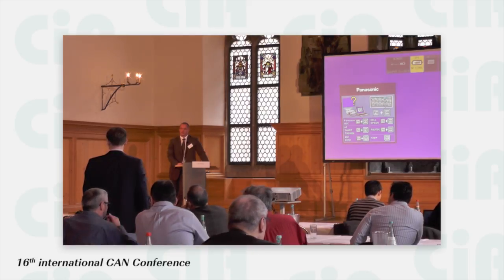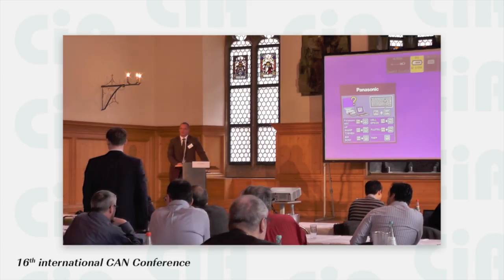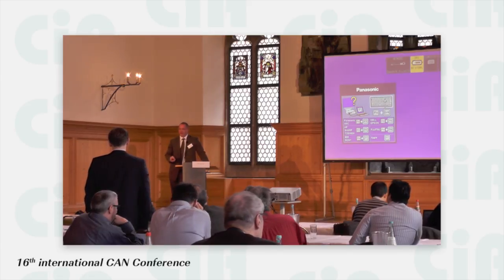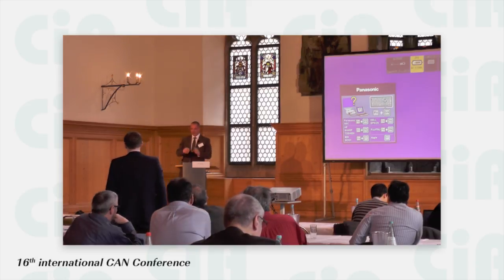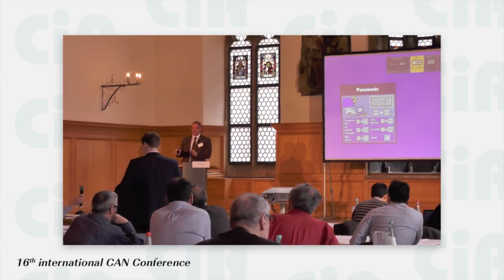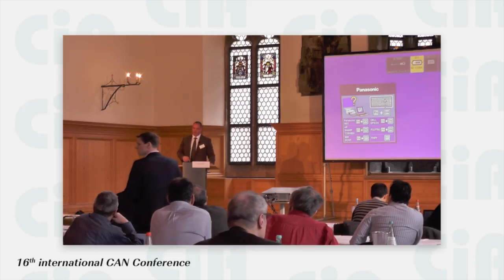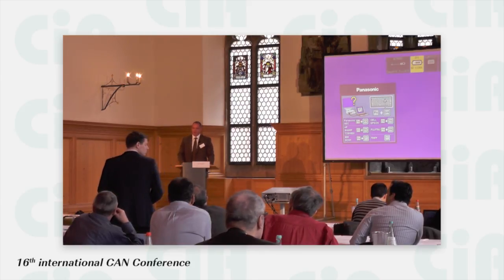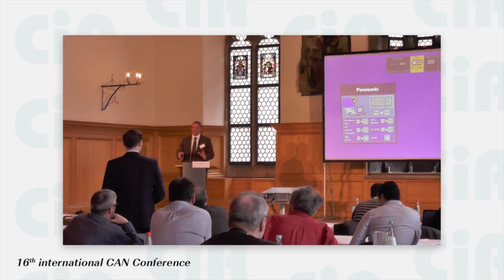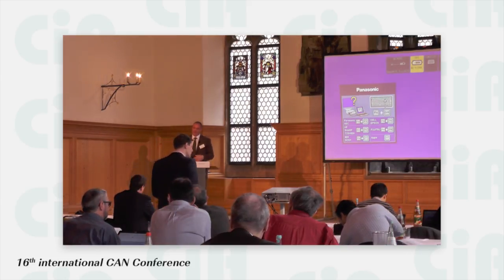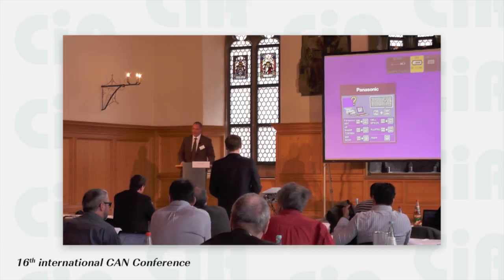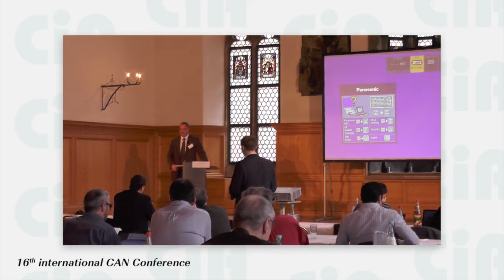Because even if the eye diagram looks good, the communication may fail because the receiving transceiver may disturb the signal. Normally, as we already discussed, we have to establish a test matrix and measure between every node, and we also have to measure the receive pin, and the test scenario would be more complex. At the moment we haven't implemented this, but that would be an outlook for future analysis.